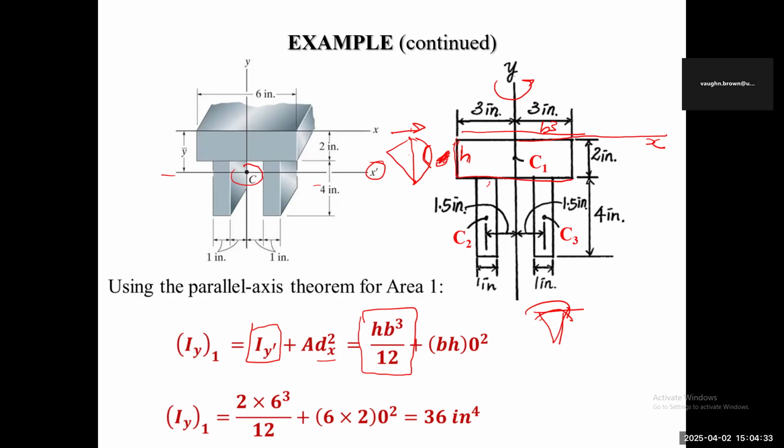Because always the height is going to be what is cubed, and the base is what will be standard. So that's how I have remembered it for many years. Once I write BD cubed, once I'm looking and I say that this is the base, this is my height, I keep it. In other words, I don't write it like this. So I can remember that anytime for any one of the axes because I keep it standard. I just say base times the height cubed.